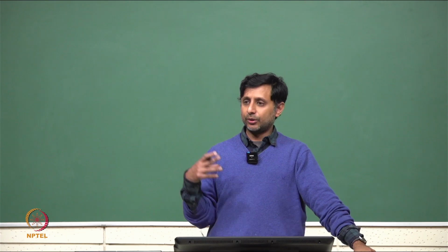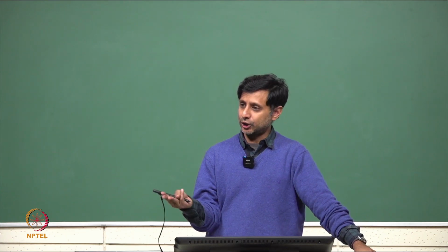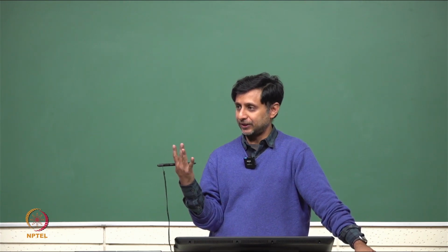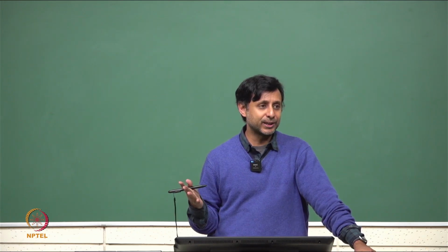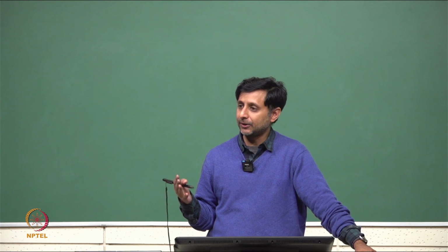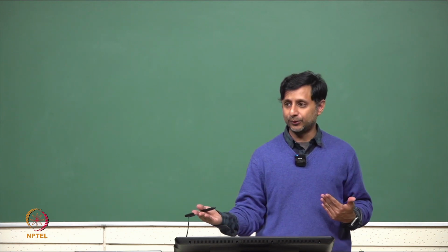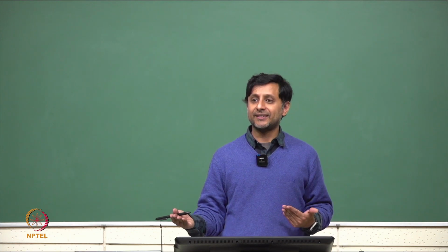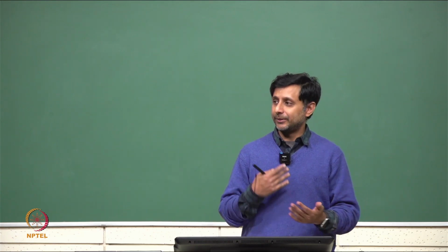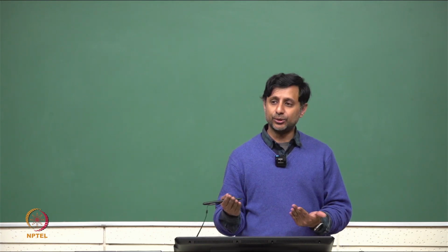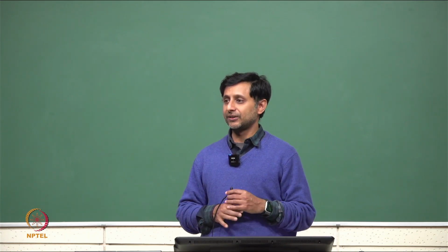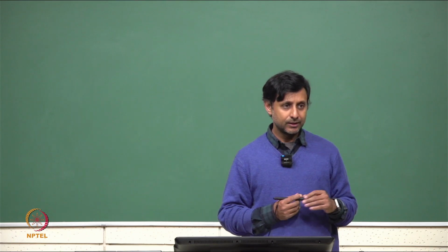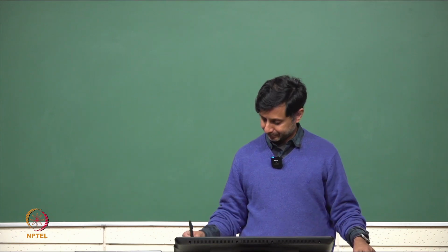All right. So, we have series, shunt, these are the 4 different topologies. The 4 different topologies go with 4 different sets of 2 port parameters. So, whenever shunt, you are going to use y, whenever series, you are going to use z, whenever series shunt, you are going to use h, whenever shunt series, you are going to use g parameters. All right, this is the overall plan.